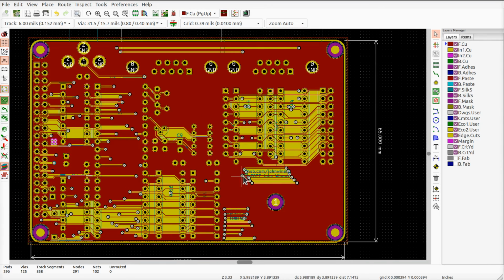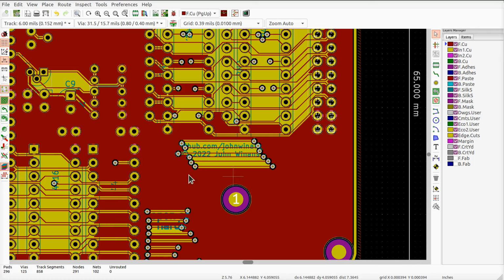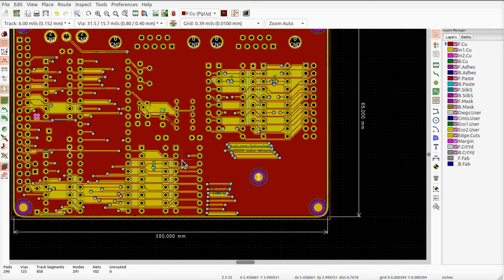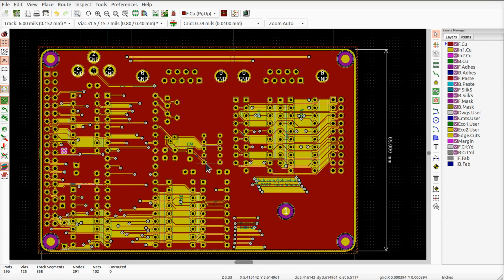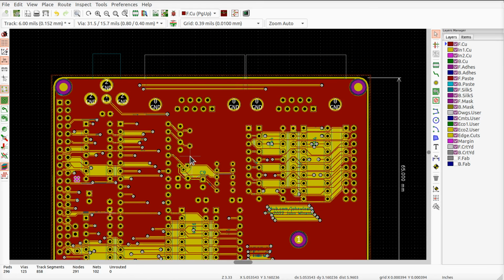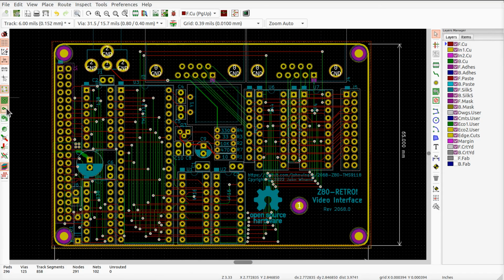Yeah, because when you bump up like this, go over and then go back onto the back of the board, these kind of jumps, this one here and these here, I might want to put some, as I like to say when I had other people routing my boards, throw some bullet holes in over here, to help that situation out a little bit. But I'm pretty sure this board will go. Might be noisy. I'll probably have a flaw in here, but like I said, I'd like to just see what happens when we run the board without 6-inch long jumper wires on my breadboard and see what happens.